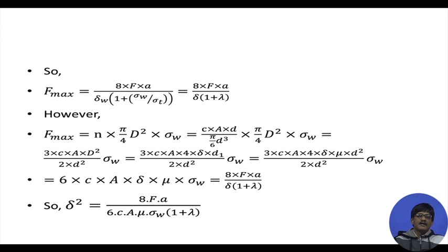That's good. Now, if we divide it by the volume of an individual abrasive, we will get the number of abrasives. So, we divide it by 4 by 3 pi r cube. We are not using r, but we are using d, and therefore it comes out to be pi by 6 into d cube. So that is written at the bottom: C A D divided by pi by 6 d cube. That gives us the expression of the number of abrasives participating in the machining process at a particular point in time.